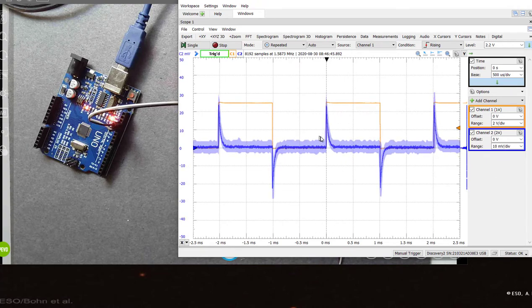And so we see the peak to peak, let's see, it's 10, 20, maybe 30 millivolts plus 30 millivolts minus. So that's 60 millivolts plus and minus. And the signal coming out of the Arduino is 5 volts. And so we see that noise is roughly about 50 millivolts out of 5 volts, about 1%. It's not a lot, but it is very clear and present.